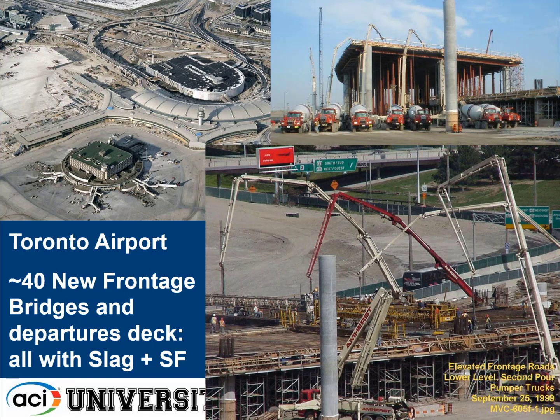Again, a view of one of the departure decks being placed here, with multiple pumps, and a whole bunch of pumps on one of the other bridge decks. And that's the new terminal there. That's the big parking garage when it was still under construction, with all these bridge decks. And this terminal was later demolished, and that was all used as our recycled concrete aggregate for all the new runways and taxiways. But anyway, all this concrete had slag and silica fume. The parking garage just had slag.